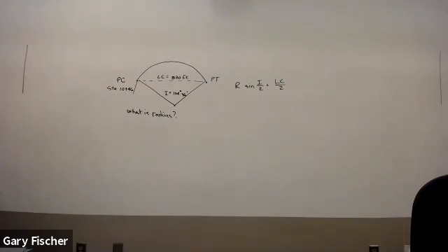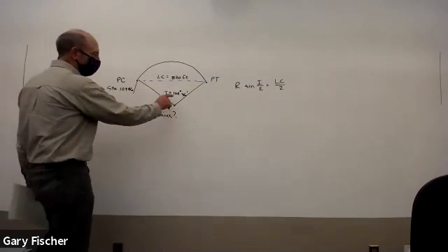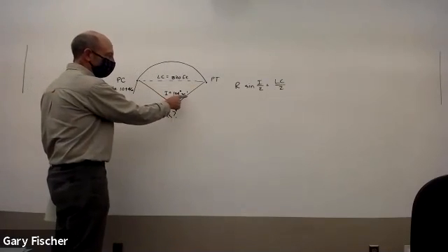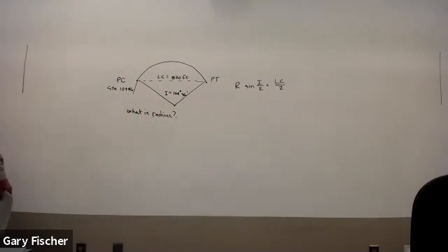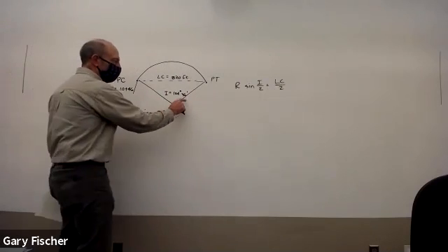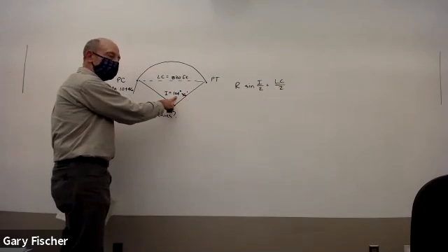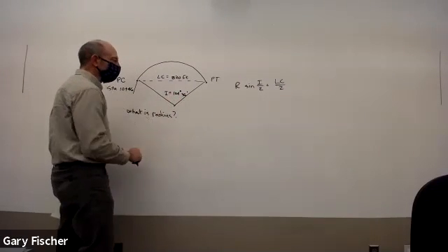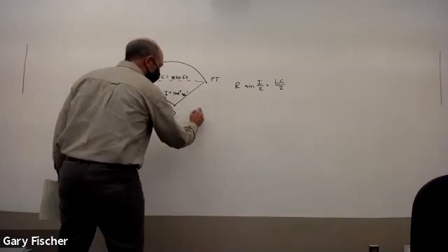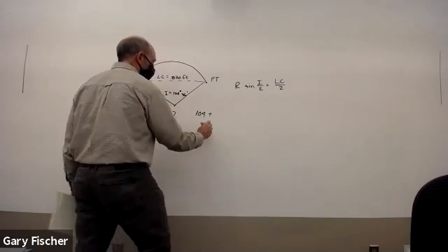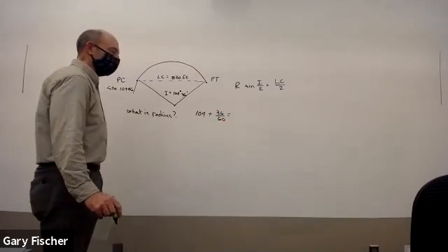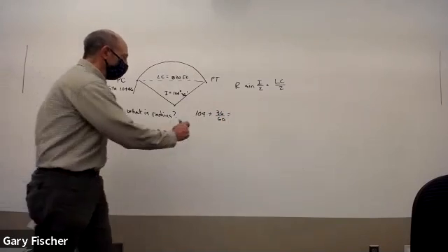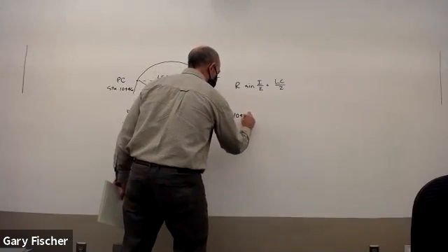So you can plug those in. There's some conversions you need to do. If you have an angle measured in degrees, minutes, seconds, this is in degrees and minutes. Do you know what those mean? There are 60 minutes in a degree and 60 seconds in a minute. So to convert that, you would have 104 plus 36 divided by 60. What's that? 0.6. Okay, so it's 104.6 degrees.